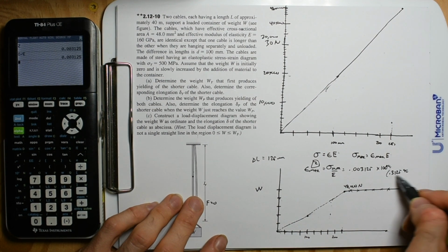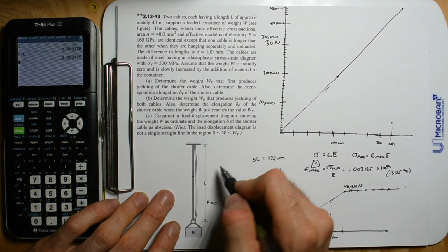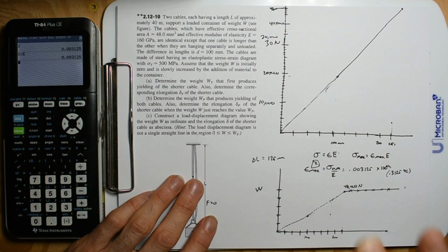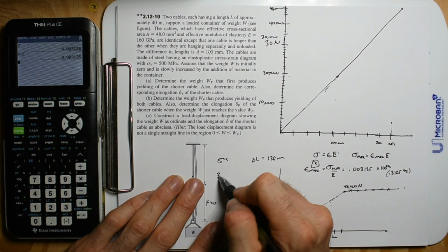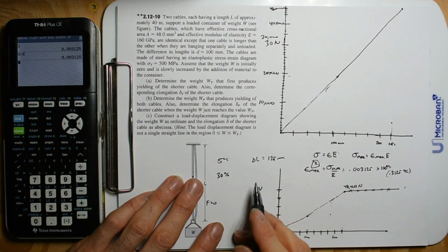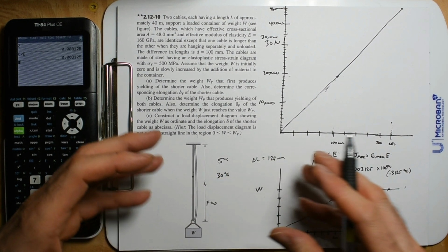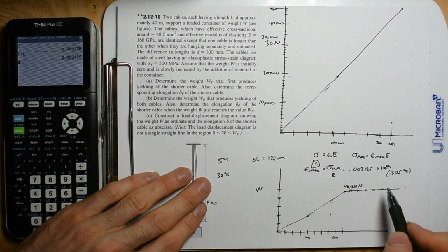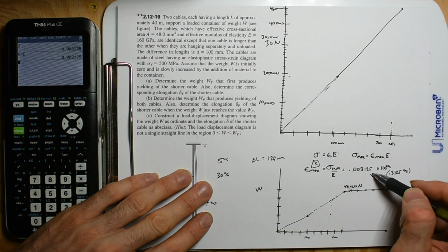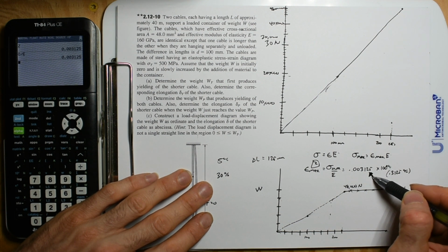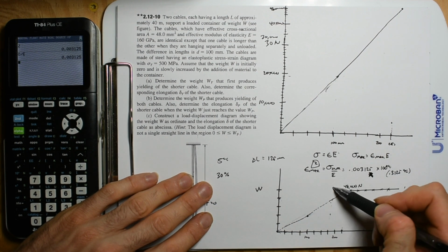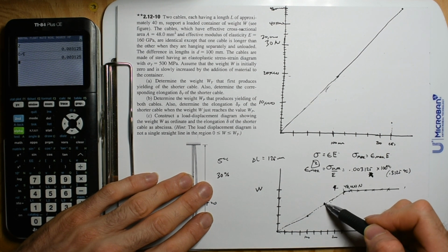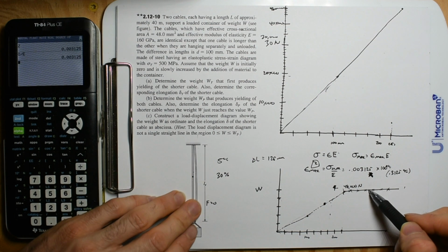Well, what do we know about steel? We know that steel can for sure elongate 5%. Some specimens of steel can elongate up to 30%. You know what I mean? So they have a plastic range. Now, if you're elongating more than this number, you're probably going to kill people. If you're designing things, you just have to stay within, like, everything on this side is your factor of safety. Land right there. Never land out here.